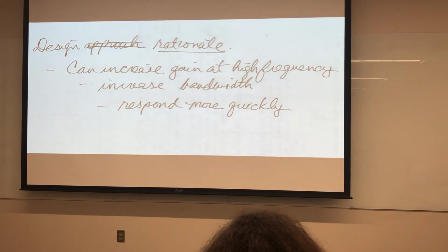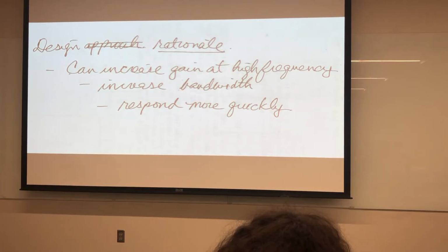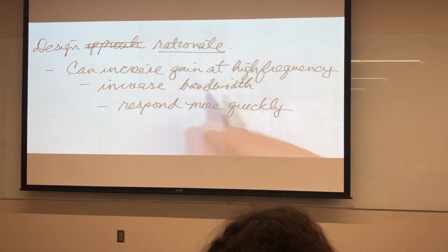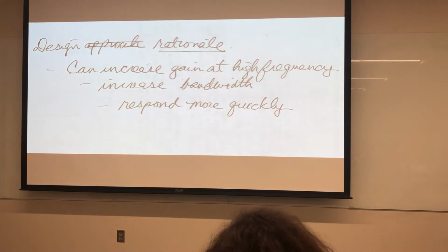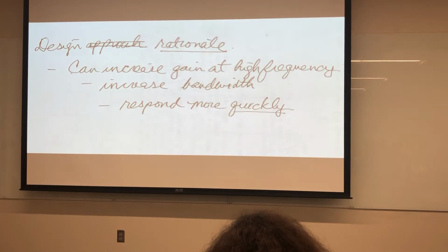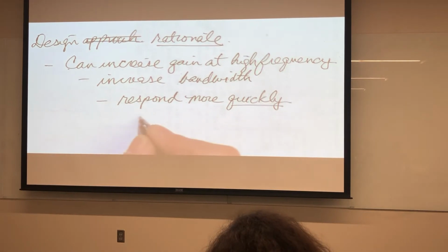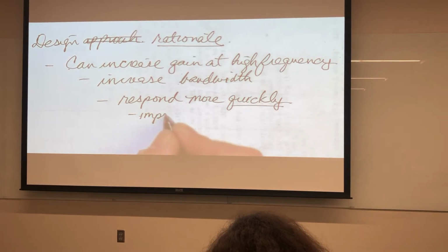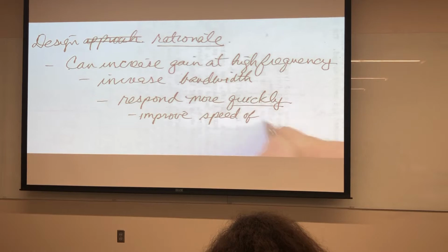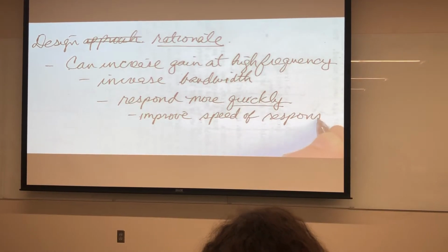Okay? If we have a control system that's responding sluggishly and we would like it to respond more quickly, then a phase lead makes sense, okay? Because it could increase the bandwidth. It does that by increasing the gain at high frequency. Okay, we can improve the speed of response.